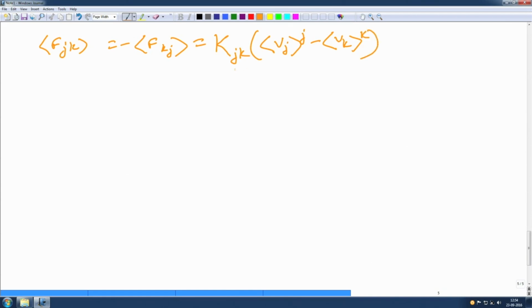This is called the momentum exchange coefficient. So, this essentially means that this is an ad hoc kind of term, and these are the velocities, the intrinsic phase average velocity in the two phases. So, this is a momentum averaged quantity.